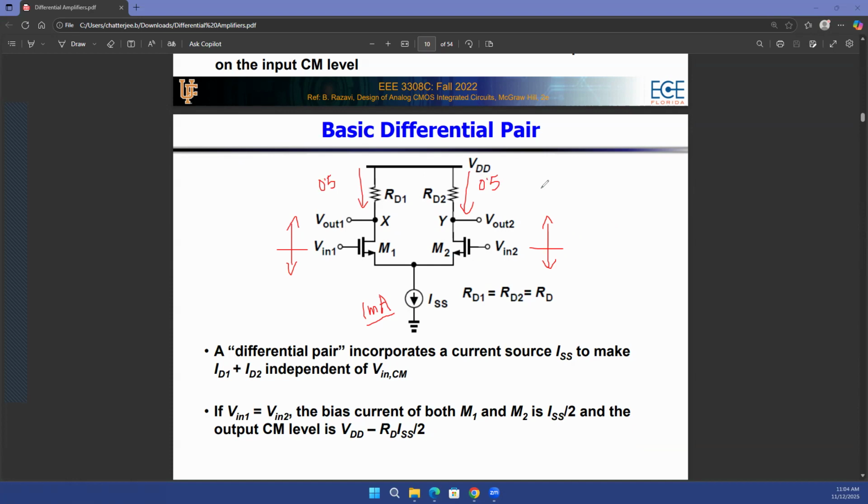So what does that tell us? It says that if I want to calculate the GM of, let's say, transistor M1 or transistor M2, you can always apply any of those three formulas for GM. Remember that GM is equal to beta times VOV, or K times VOV. GM can also be written in terms of square root of twice beta times ID. It can also be written in the form of twice ID over VOV.